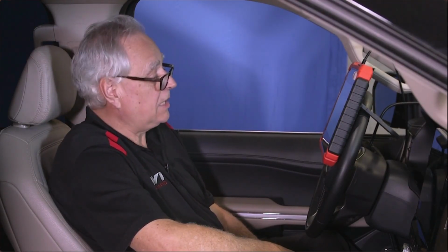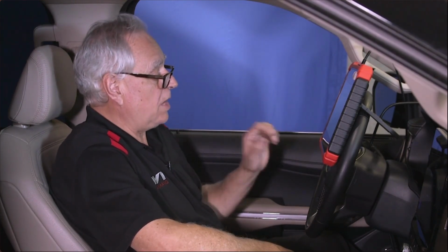If this was a non-turbocharged V6, instead of turbocharged like it is, the cranking RPM would probably be about 240 or so. So that's a difference. A lot of people think because it's got a turbo, it's going to take more to crank. It does not. Compression ratios on turbo vehicles are statistically lower, so we can introduce a bunch of boost into it without having issues. Okay, so there's your relative compression test.